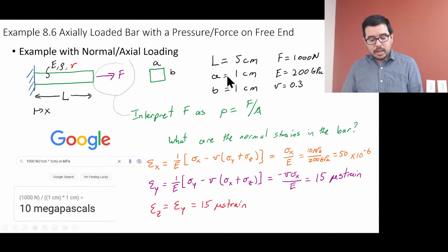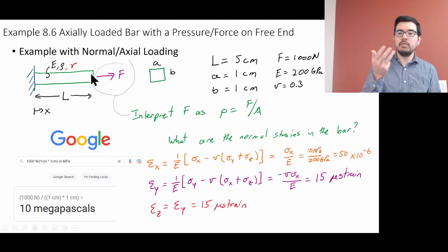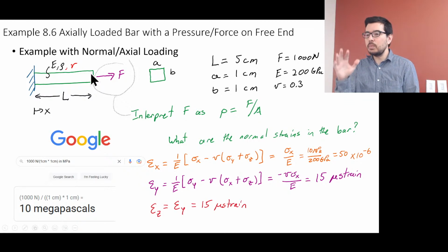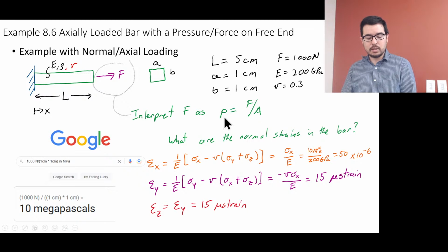Now, sometimes with finite element, it doesn't like it if you put a big point force load on it. Okay. So sometimes you need to distribute the force. But we know how to distribute the force. We can distribute it as a pressure. It's just force divided by this cross-sectional area. Okay? And that is going to be the stress along this bar, right? We agree, right? Sigma, if this is x, sigma x is just going to be this force divided by its cross-sectional area.